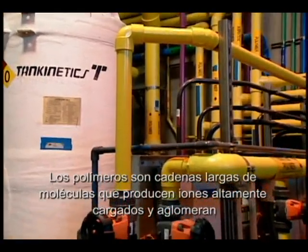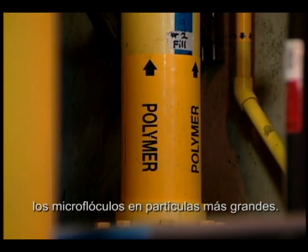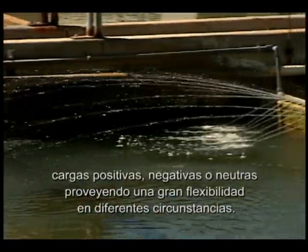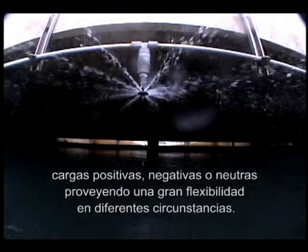Polymers are long chains of molecules that produce highly charged ions and help bind microfloc together into larger floc particles. They have become very popular with operators because they can be positive, negative, or neutrally charged, providing a great deal of flexibility in different circumstances.